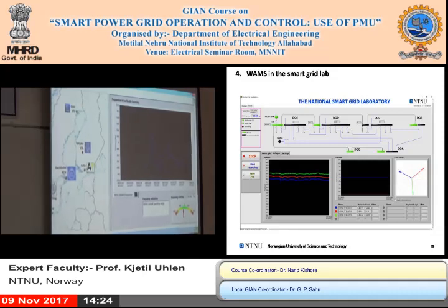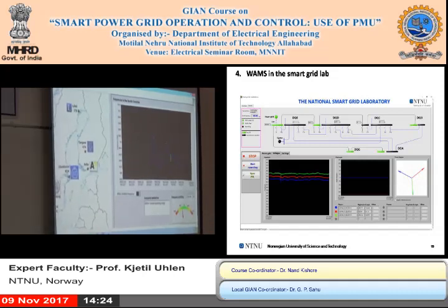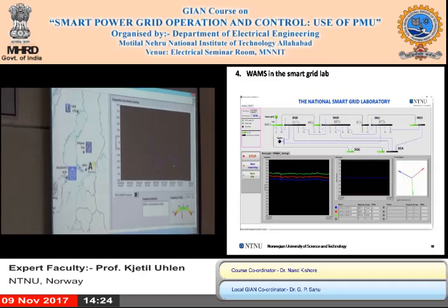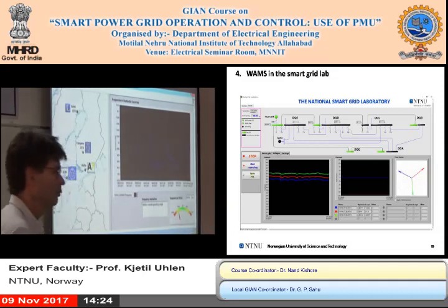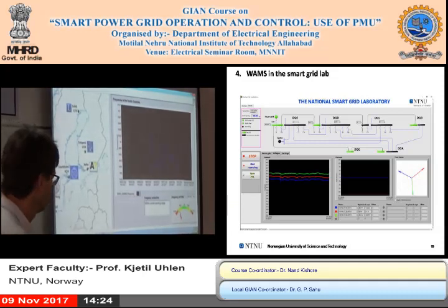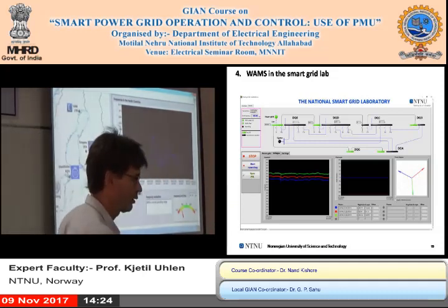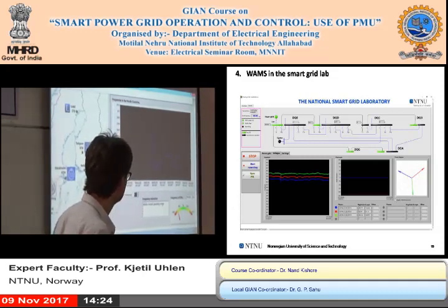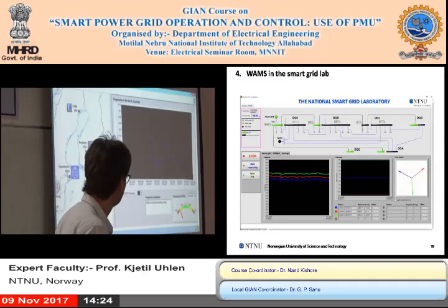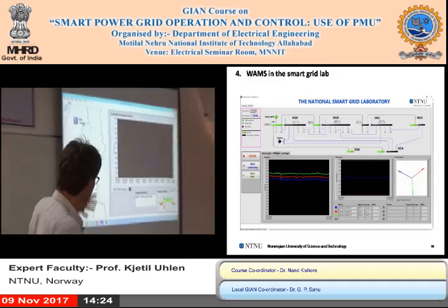This is typical for the Nordic power system, that you have these slow oscillations in frequency, which I believe, and many believe, is due to the way the hydro plant governors are sort of slow, so they have a natural frequency and sort of a resonance frequency in the range of 1 minute.